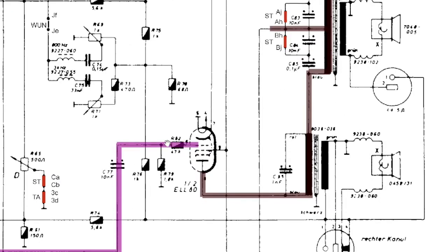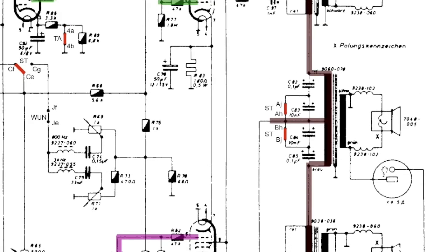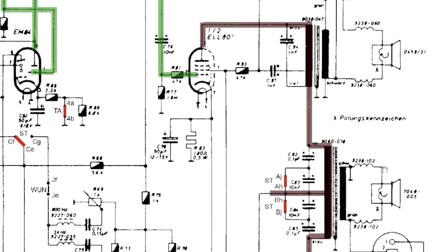The same occurs with the other channel. The sound is induced in this transformer, bypasses that one through that high-capacity capacitor that we have here, and it induces that signal, that sound, on this speaker. So we've basically got ourselves a push-pull and two single-ended amplifiers here.